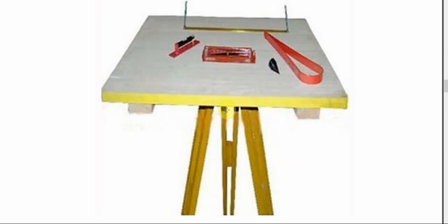So this ball and socket joint with a vertical spindle helps the table to rotate about a vertical axis and also to move the table about a center point in the vertical plane so that it can be leveled easily. The Johnson table can be leveled very easily compared to the traverse table. If you want to level the Johnson table, you can use the ball and socket arrangement.